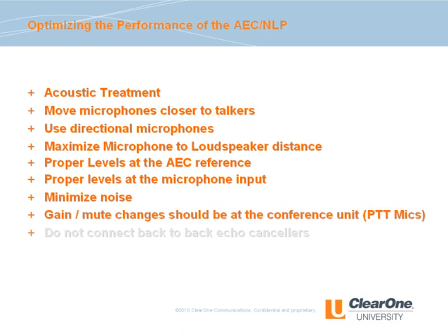Volume and mute changes should be done at the conference unit. For example, push-to-talk mics should control the conference unit mute and not the mute at the mic. Muting at the mic will cause echo each time the mic is muted or unmuted. This is because the AEC reference will not see the change. Muting within the conference unit will eliminate this problem. The exception is to use push-to-talk mode, available in the ClearOne Converge Pro and Interact conference systems.